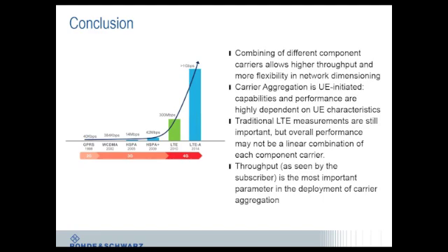Traditional LTE measurements are still important because there are no such things as carrier aggregation towers or carrier aggregation bands, and overall performance may not be a linear combination of each component carrier. It is necessary to test each carrier individually and simultaneously.